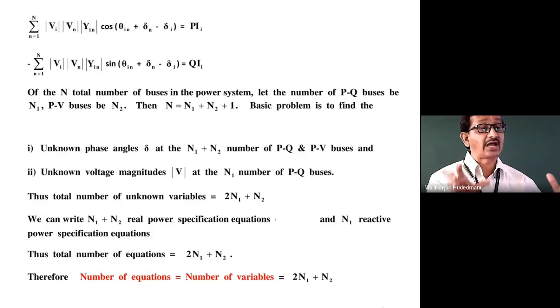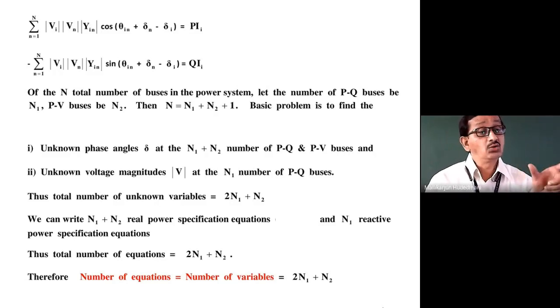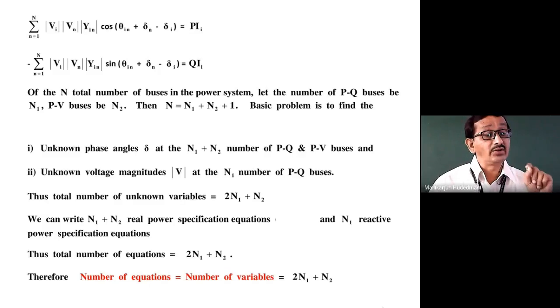How many load buses do I find in this description? Say N1, like 50 in my statement. Suppose I have N1 load buses, so N1 voltages are not known to me. I have to solve them. To solve them, N1 times I should solve the QI equation pertaining to buses 7, 10, 12, 50, something like that number. So that Q equation I should touch only N1 times.